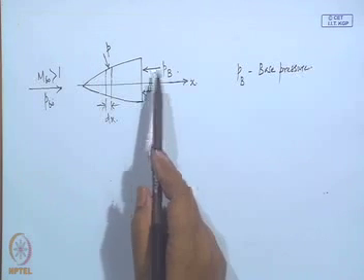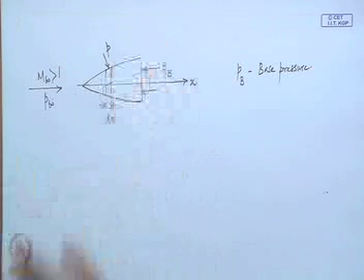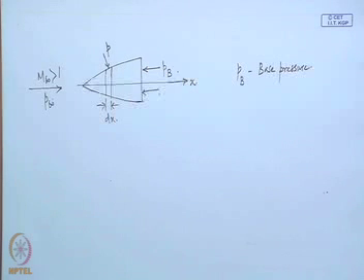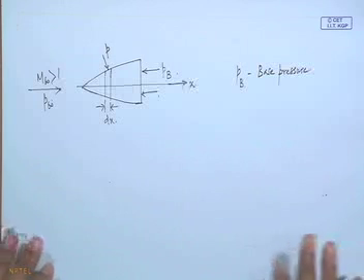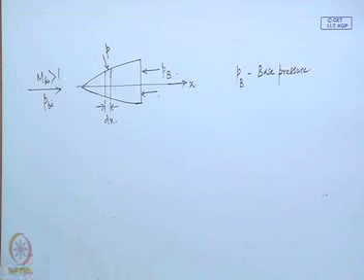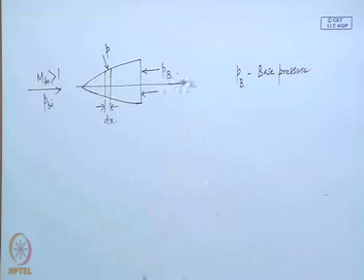However, as far as the back pressure is concerned, we cannot evaluate it based on this inviscid flow theory, because flow behind this body with a blunt base is always highly viscous, even maybe turbulent, and cannot be evaluated by any inviscid flow theory. So, this P b can only be obtained using either a full viscous flow theory or by experiment.